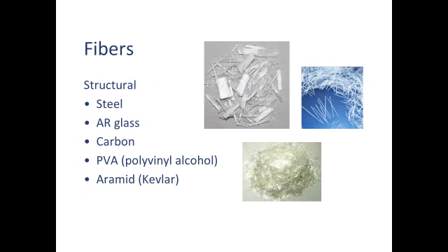Structural fibers, on the other hand, do provide true tensile reinforcement, and that's why GFRC uses an alkaline-resistant glass fiber. It's a structural fiber, very high tensile strength, very, very stiff, not stretchy at all. Carbon fibers are the stiffest. It's called the modulus of the fiber. Steel has a modulus of about 30 million psi. Carbon fiber can be 2 to 3 or 10 times that. Glass is about 1/3 of this. Glass is about 3 times stretchier than steel, but it's still very, very stiff relative to the cement that encapsulates the fibers.